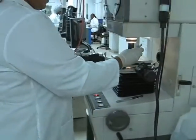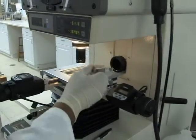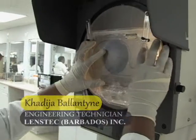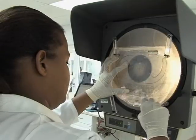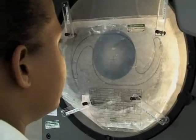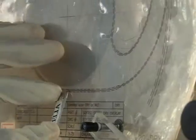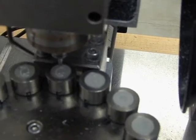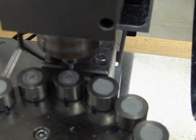This is done by placing the lens onto the profile projector and utilizing an AutoCAD drawing. As you know, AutoCAD is basically a computer-aided drawing. Once the AutoCAD drawing is placed onto the profile projector, the lens is focused and adjusted to fit into the drawing. Measurements are then taken to ensure that the lens is within the tolerance range allowed. If the lens is too big or too small or falls outside of the tolerance range, the technician returns to the milling machine and readjusts the program, and the process is repeated until the lens falls within the specification or tolerance range.